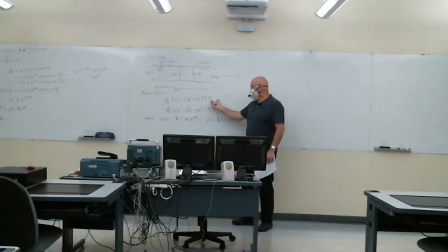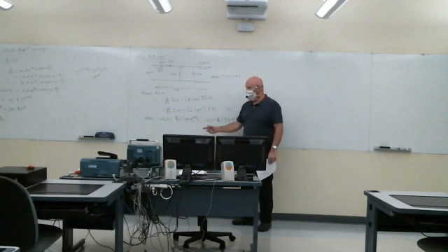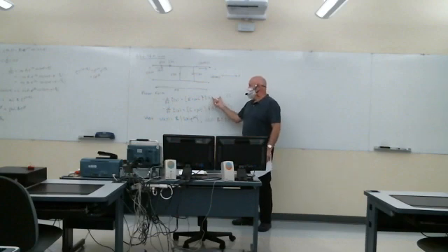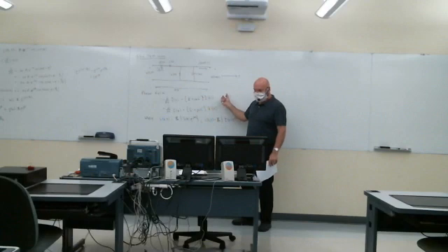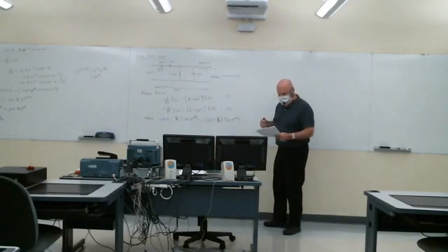And on the right-hand side of equation 1, you'll get this term times the partial derivative of I with respect to z. Well, we've got an expression for the partial derivative of I with respect to z in equation 2. So if I now make this substitution back into the derivative of equation 1, I'll have a single equation involving only my voltage phasor.